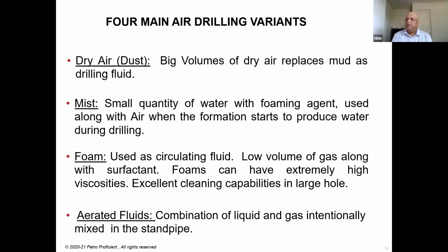The next technique that is part of this group is foam drilling. Now, foam is used as a circulating fluid, basically a low volume of gas along with surfactant. The advantage of using foam is that it has high viscosity and excellent hole cleaning capacity.